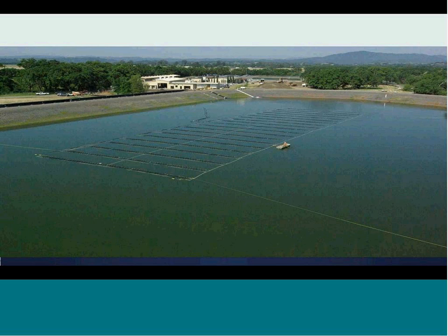This system also uses cement blocks to weight the system down to the bottom of the pond. In most pond applications, the pipe is kept above the bottom of the pond, so sediment has less opportunity to foul the pipe. In this particular design, the idea was that it would be a hybrid slinky/pond loop heat exchanger that was sunk directly to the bottom of the pond to try and take advantage of the available conductive heat transfer with the bottom of the pond surface, in addition to the convective heat transfer, which is basically the feature of these different surface water systems, including the pond type.